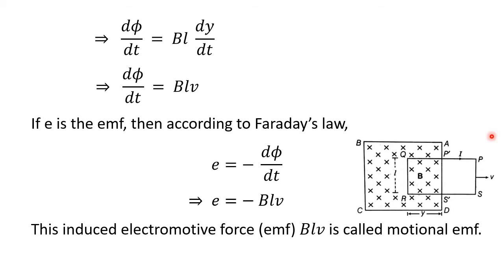Now if you analyze the diagram, as the conductor is moving perpendicularly in the magnetic field, there is an EMF across these terminals. Due to that, current will pass. The induced EMF is generated, and with respect to that, current will pass. The current direction we can analyze with respect to the change of flux. For example, here the coil doesn't want to change the magnetic flux. As we are moving this to the right side, flux is decreasing continuously. So the coil doesn't like to change the flux in the area. That is why it will generate flux in the same direction